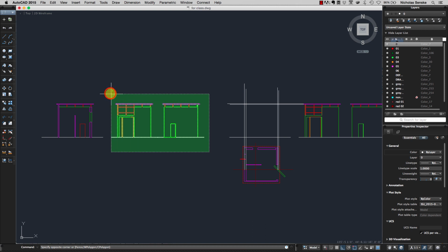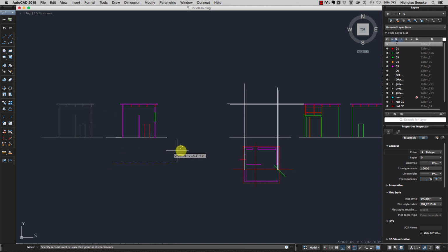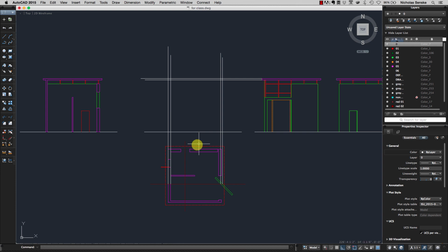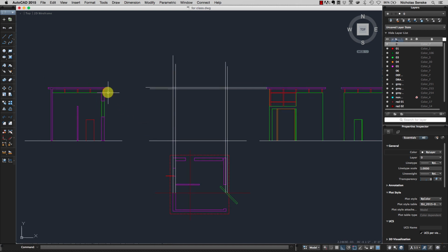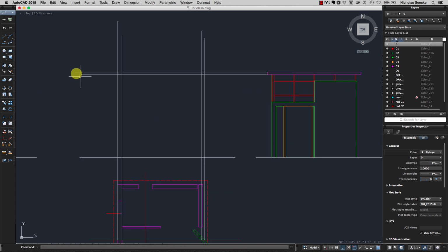In fact, I already got my elevations. I'm going to go ahead and kill these, and we're going to move this over. Orthographic projection is really useful for constructing drawings, but it's also useful for thinking about your design. One of the principles in architecture is carrying different lines across a design, across different walls. If I know what the height of something internally is, I can use that dimension when I design. So it's not just making this drawing for the sake of making the drawing. It's actually thinking about how the space works.